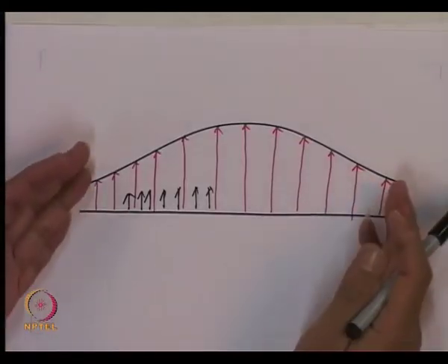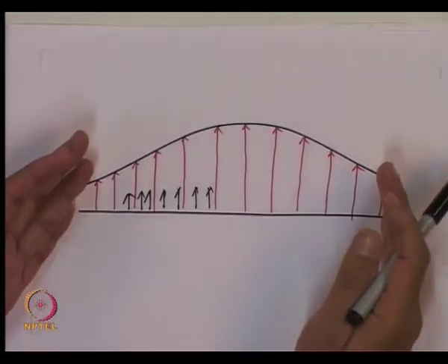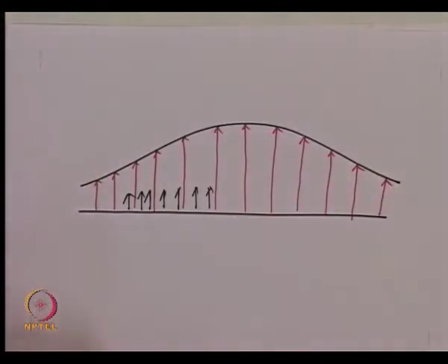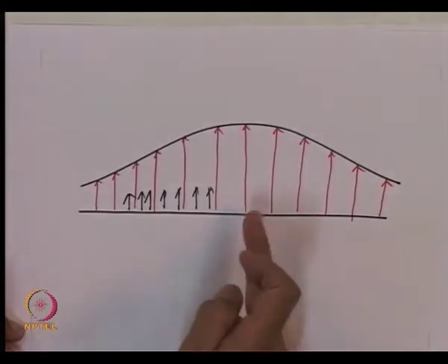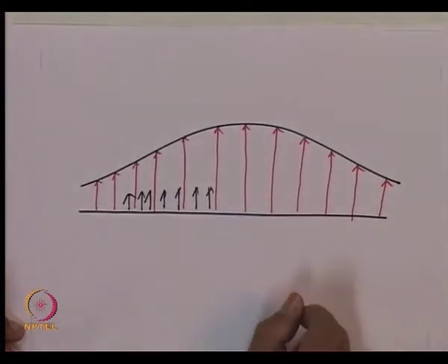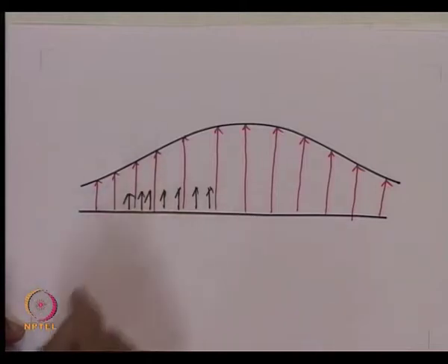However, since we are having a spectral width which is large, typically of the order of a few hundred gigahertz, the pulse which rides on this carrier would travel with a different velocity than the pulse which rides on this carrier, because if we take the material intrinsically, the refractive index is a function of wavelength.